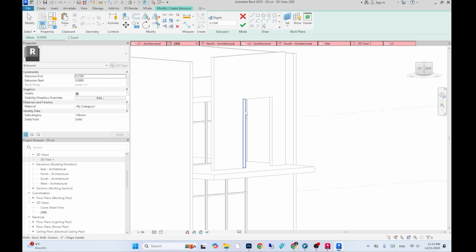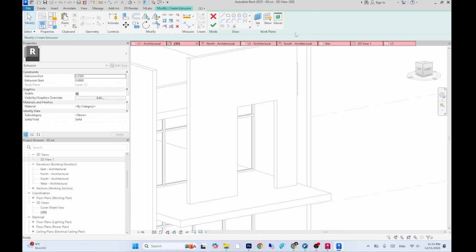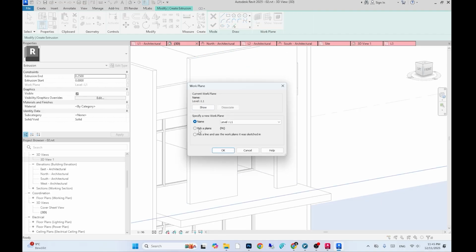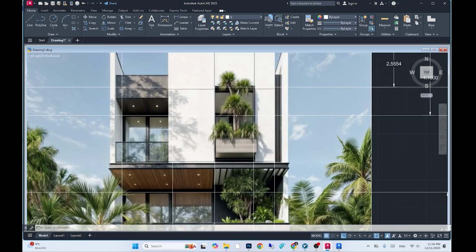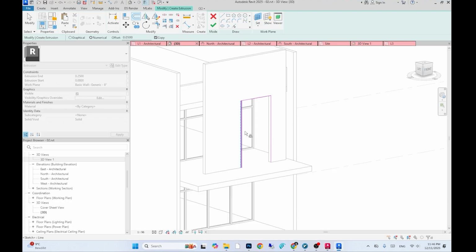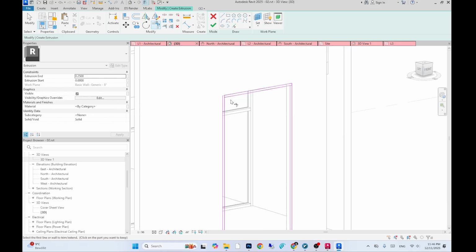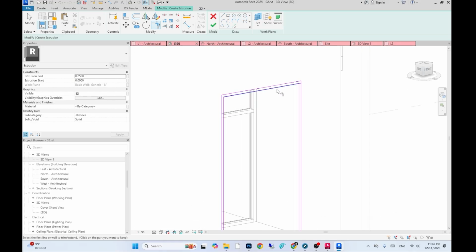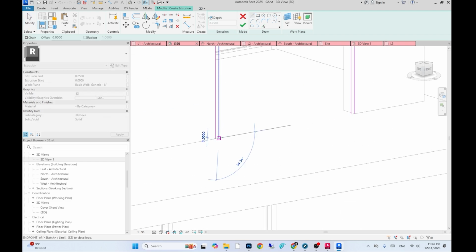In this step, we want to create the sheet elements that wrap around this opening. So we set the work plane on this wall. Then, use an extrude and the edge of this geometry as a reference. We draw the metal sheet. After picking this line, we give the sheet a thickness using offset. Connect all the lines with the fillet and then confirm the sketch.